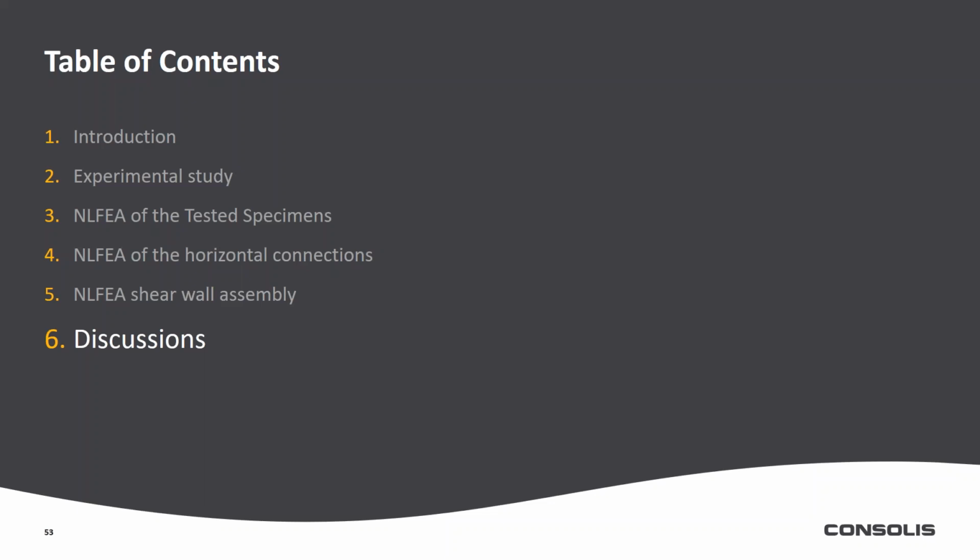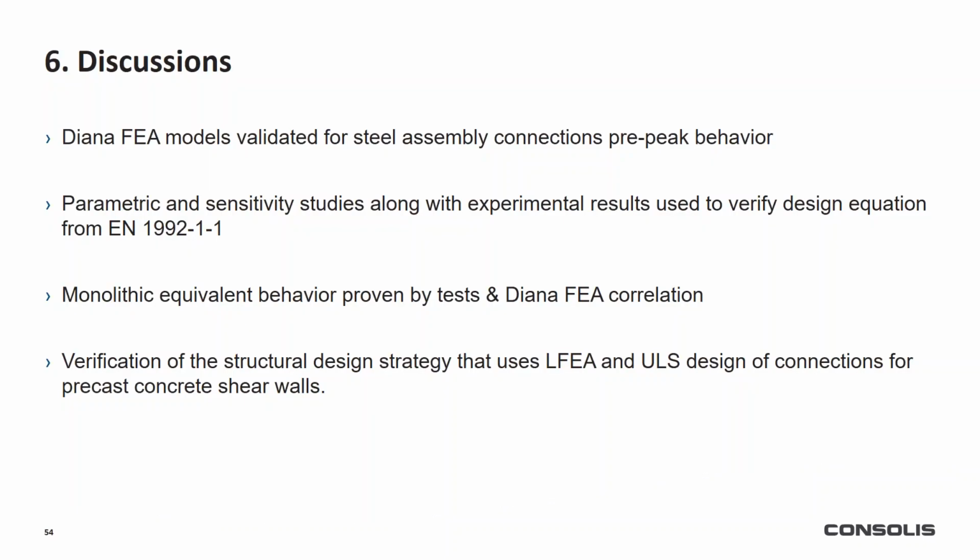So that was it. After the analysis, we would have some discussions. So, Diana models were validated for the steel assemblies connections for the pre-peak behavior, and by using parametric and sensitivity studies, we were able to verify the design equation that is provided by Eurocode